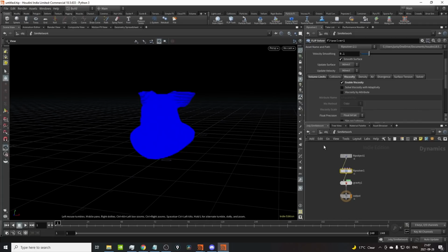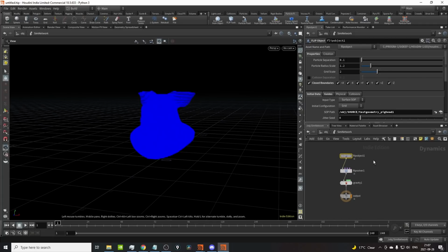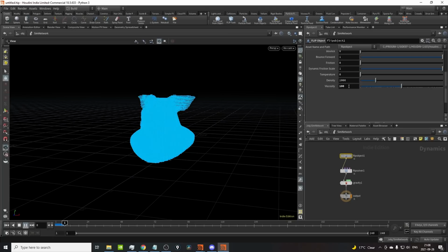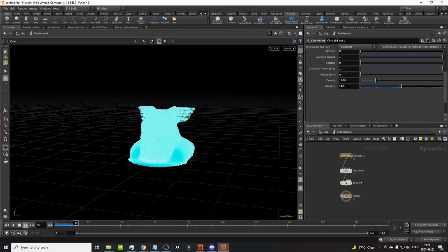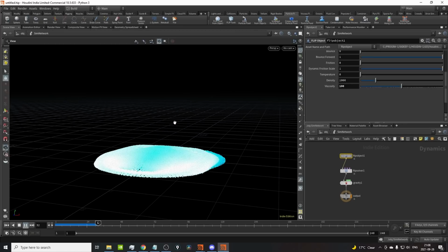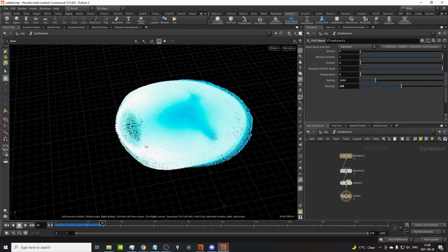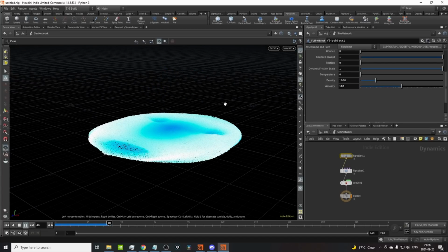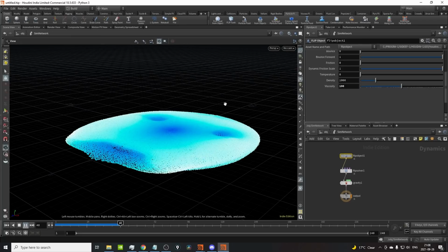All the same value. So the way we do that is on the flip object. On the physical options, you see viscosity here. That just gives the whole container, all the water, the same viscosity value. So we're going to give this 100 to begin with, and let's hit sim on that. And now we can see that everything is still falling apart and it's still squashing, but it's doing so a lot less, right? The water is no longer rushing to the sides and floating away. It is just kind of trying to stay together.